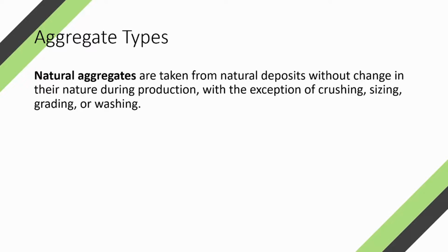Included sa mga natural aggregate is yung mga crushed stone, gravel, sand. So, yan yung mga common na natural aggregates natin. And we may also include yung mga pumice, shells, iron ore, and mga lime rock natin. So, these are natural aggregates. So, yung process niya lang dito is yung crushing natin, sizing, grading, or washing.